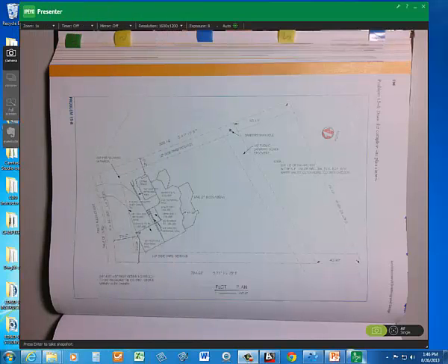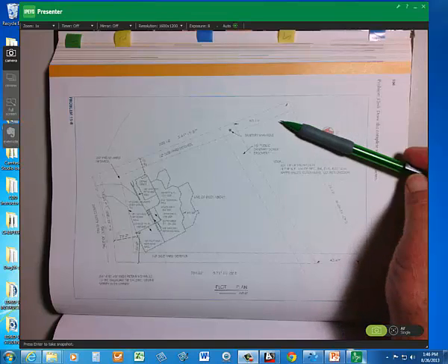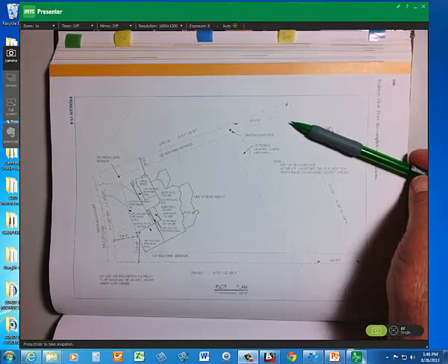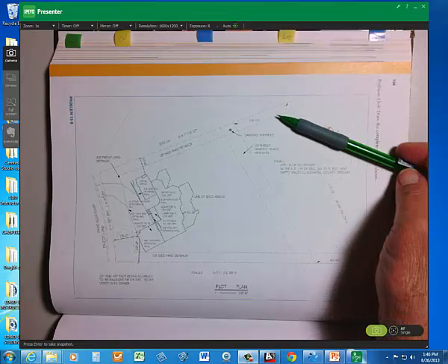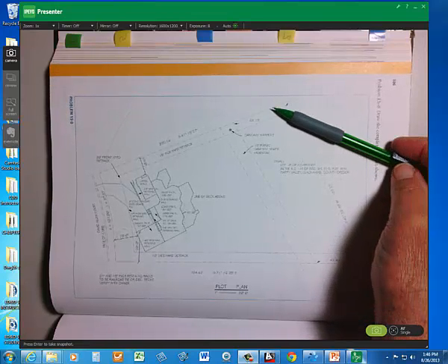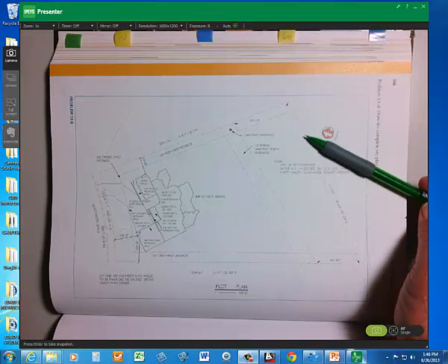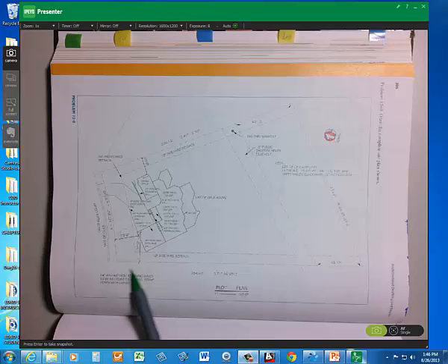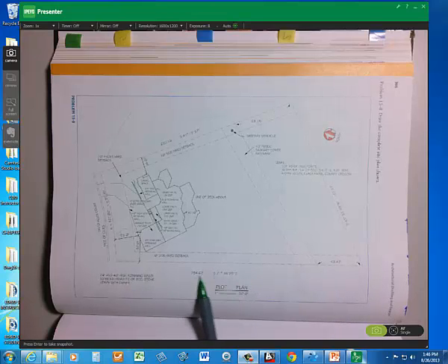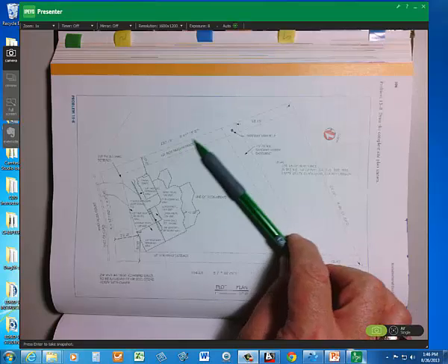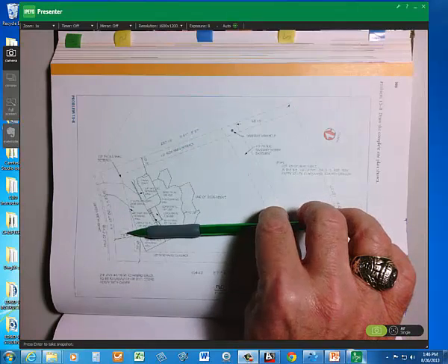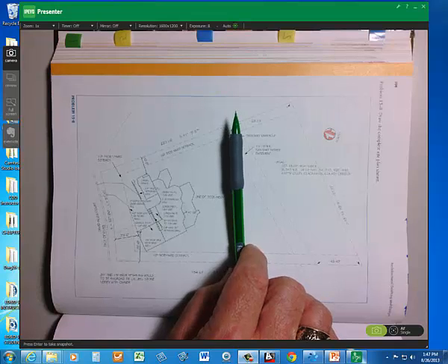Going over the review of the problem assignment, problem 15.8 and 15.9. As you begin to lay this out, remember when you draw it, this is the north arrow, which will become vertical in your CAD screen. Okay? So when you lay out these lines, you will need to lay them out using the bearings that are indicated here. So this will be oriented nearly vertical.